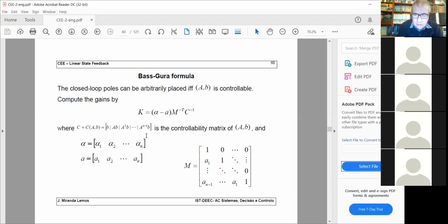There are reasons why it should not work. If you have disturbances, that's one reason. Feedback attenuates the disturbance, the effect of the disturbance. Also, you can have an open loop unstable system. And if you have an open loop unstable system, you would never reach steady state. So you want to place the poles of the closed loop such that the control system is stable. Okay?